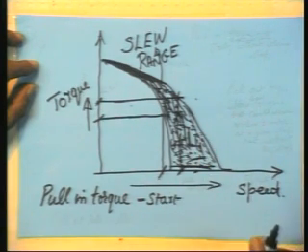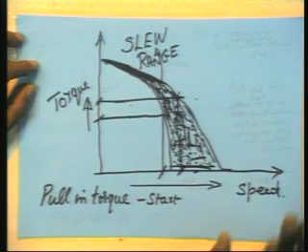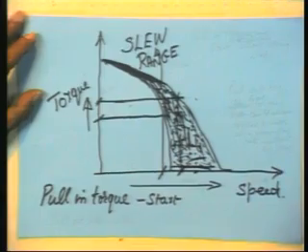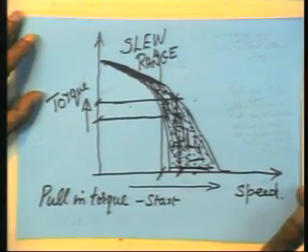So these are the points you have to bear in mind when you select a stepper motor for your drives. Now regarding calculating the size of the stepper and all, procedures are similar to what we had seen in the servo motor. Only thing you have to remember is that you have to carefully operate the stepper. If you violate these, you will lose steps. That's what it is. Now to go into the slew range and out, you have to accelerate very slowly or decelerate very slowly.